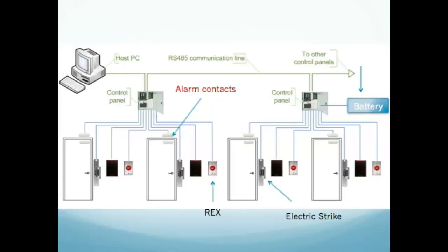From our old wiring diagram, our riser diagram that we used the last few weeks, we just added in up top here. Those are pretty big, but they're there for purposes so you can see them. But on each door, you see there are alarm contacts. There's a switch on the top and a switch on the bottom. And when these separate, it sends information to here, right? One of these boards is opening and closing the door. The other one in here has wiring for alarm inputs. And it says, if these separate, send a message back to the host to tell them that someone has breached the door. They've opened the door not using a badge.